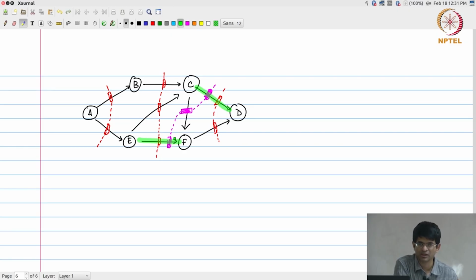On one clock cycle the data goes from the source, that is E, into one of the registers. On the next clock cycle it goes from that register to the next register, and on the third clock cycle it goes from that register to F, where the computation is done. So, some of these registers are just placeholders. They are holding data for some time until they are ready to be accepted by the next stage, making sure that the number of registers on every path from input to output is the same.